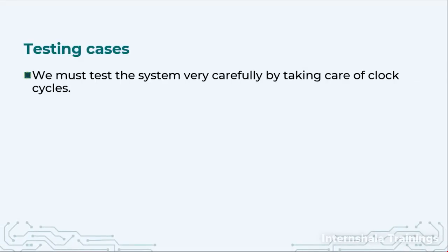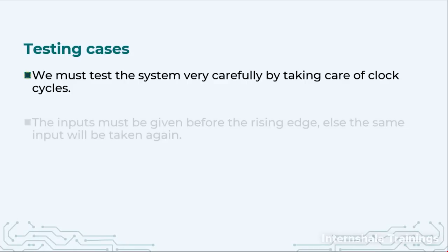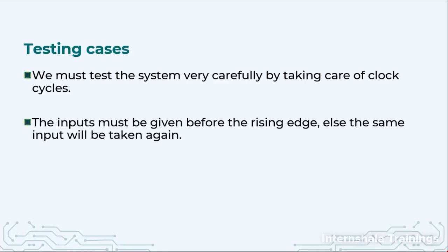So test cases should be very carefully designed, and we should test our machine very thoroughly for all possible cases. The inputs must be given before the rising edge of the clock. So when you are testing it, please make sure that your input is available before the rising edge, otherwise it will not be counted.